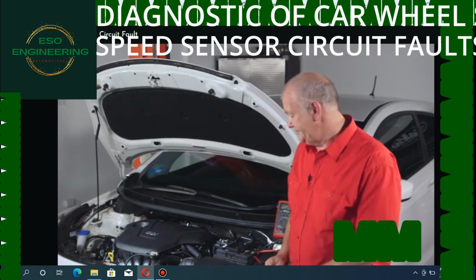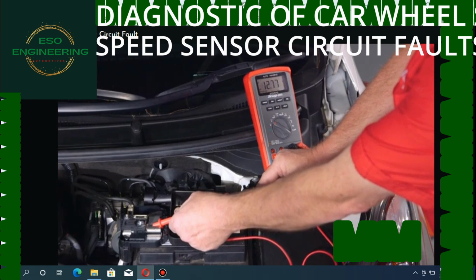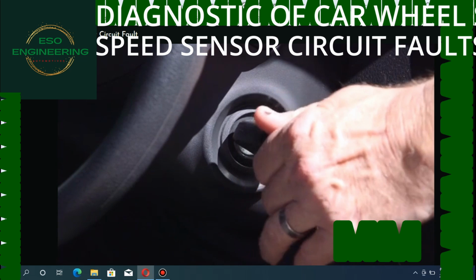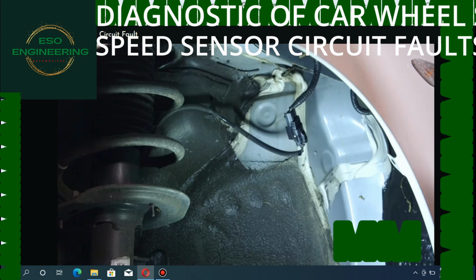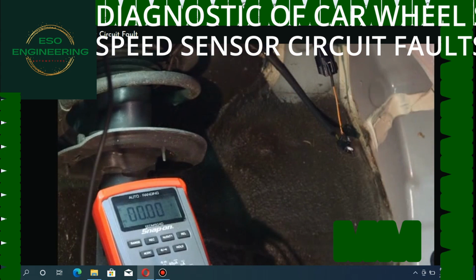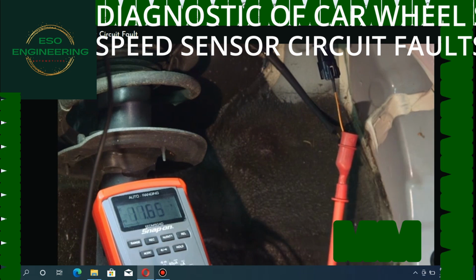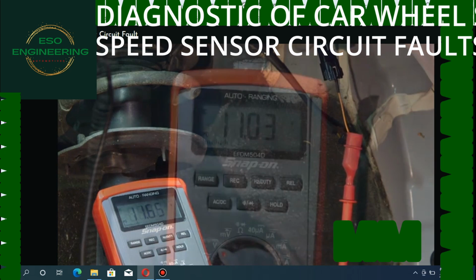Always start electrical tests by measuring the battery voltage. Most of these tests are conducted with the ignition on. Always turn the ignition off before connecting or disconnecting sensors or modules. Disconnect the appropriate wheel speed sensor. Connect the multimeter between the 12-volt reference terminal of the harness connector and battery negative. You should see approximately 12 volts.